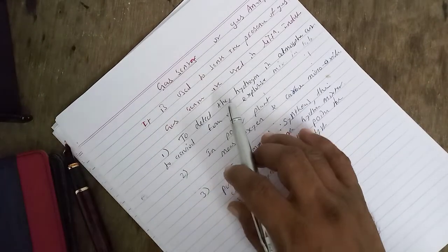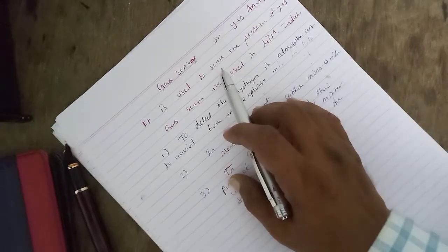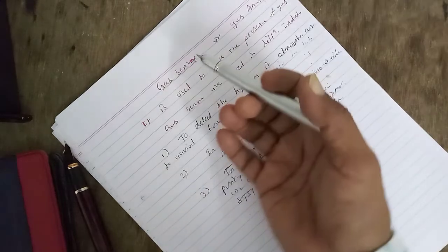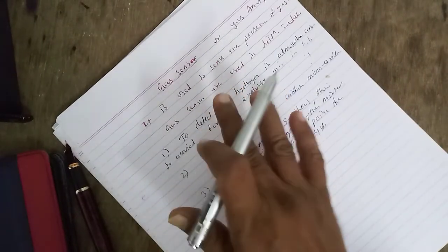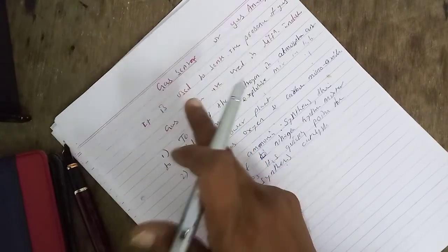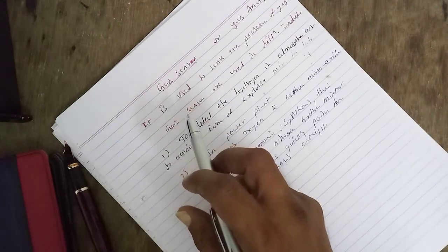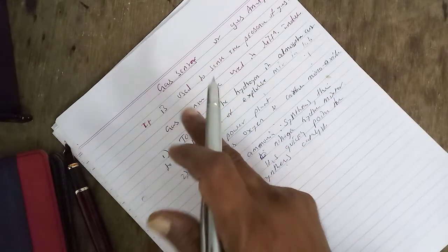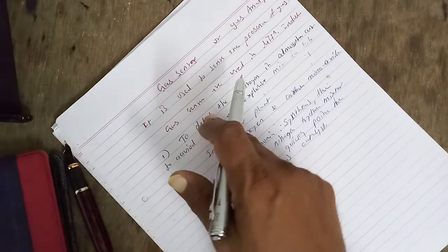It consists of analyzing chambers and measuring sections in which the measured quantity is transferred to an electrical current or voltage according to the concentration of the component to be determined. There are different types. Type 1 is a thermal conductivity analyzer using a glass protected platinum wire. The second is the paramagnetic oxygen analyzer using a glass protected heating spiral. And the third is an infrared absorption analyzer for CO2 using a diaphragm capacitor.